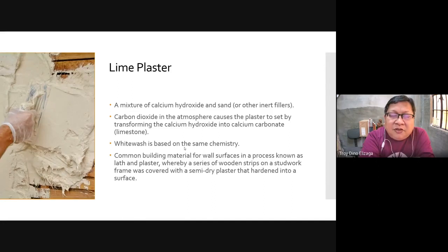to source out. In Cebu, I have a source which sells the lime powder in bags, and then we mix it with water and let it stay for a few months, and better if for a few years, no? Because the old construction, especially the very traditional houses, bahay na bato, and also the old churches, the stones in Cebu or the Visayas are made of coral stones. And you do not use cement with coral stone.